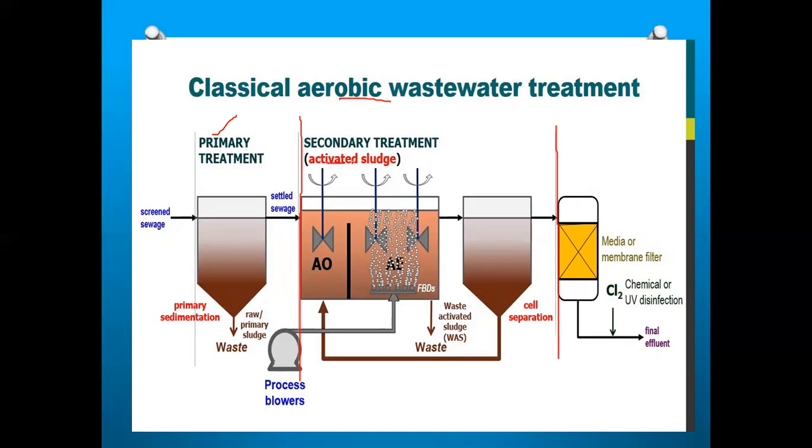In the activated sludge process, the water has to pass through the pipeline. It is passing into the clarifier or sedimentation tank, and the waste material is coming down, and again it goes through the same repetitive process. Next, after recycling, the water goes to the process where you are adding some disinfectants. That is chlorine disinfection, in this aerobic treatment process.